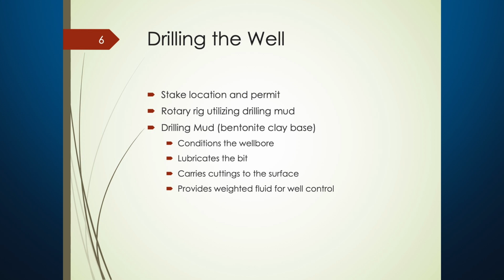We've got some cuttings you'll see at Stephanie's location. I think I've even got a bag of cuttings back there. And then it provides weighted fluid for control of the well. Has anyone ever seen any of the old movies of Tulsa, Boomtown? Any of those movies where the gushers, we don't like that. That makes a big mess. John Rockefeller back in the 20s may have sent oil down the creek trying to get it to a place where he could offload it, but we don't do that anymore. It's a hazard. We just don't do those things. So that's what the drilling mud does.